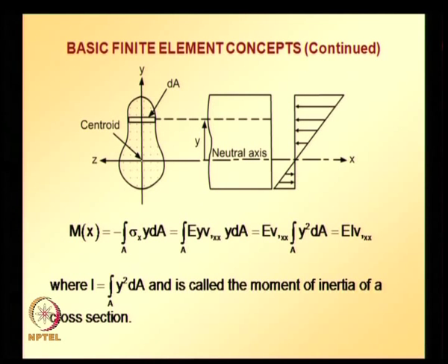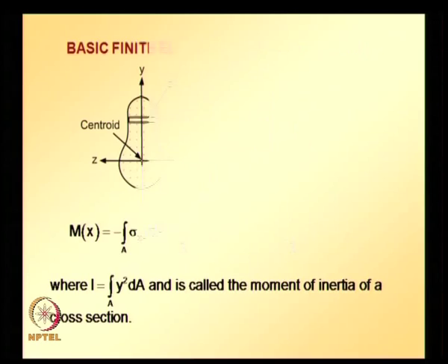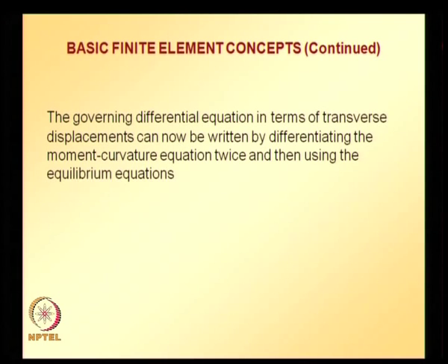So, now we got a relation between moment and transverse displacement. Please note that this is the internal moment, and earlier we have seen the relation between moment and load applied. So, we can rewrite the previous equation and obtain the governing differential equation in terms of transverse displacement. Here M is equal to EI second derivative of transverse displacement with respect to the spatial coordinate, is substituted, and we obtain this equation.